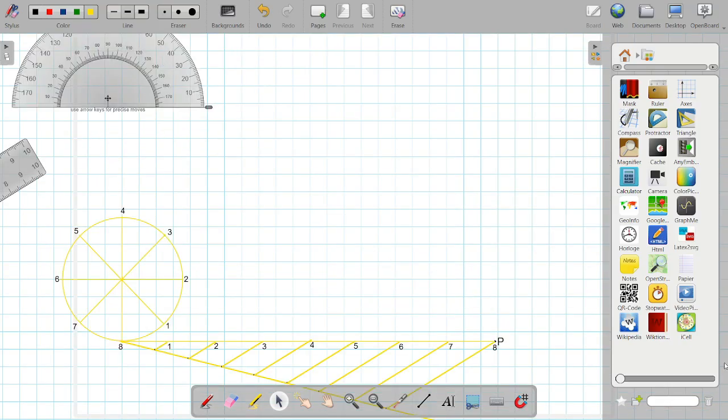Now, if you remember the cases wherein we have drawn the involute of a pentagon and a hexagon, that means any of the regular polygons, then in the next step we extended the sides, for example 1 to 2, then 2 to 3, and so on. Here, what we need to do is draw tangents to each and every point on the circle. That's the difference between the construction of an involute of polygons and an involute of a circle.